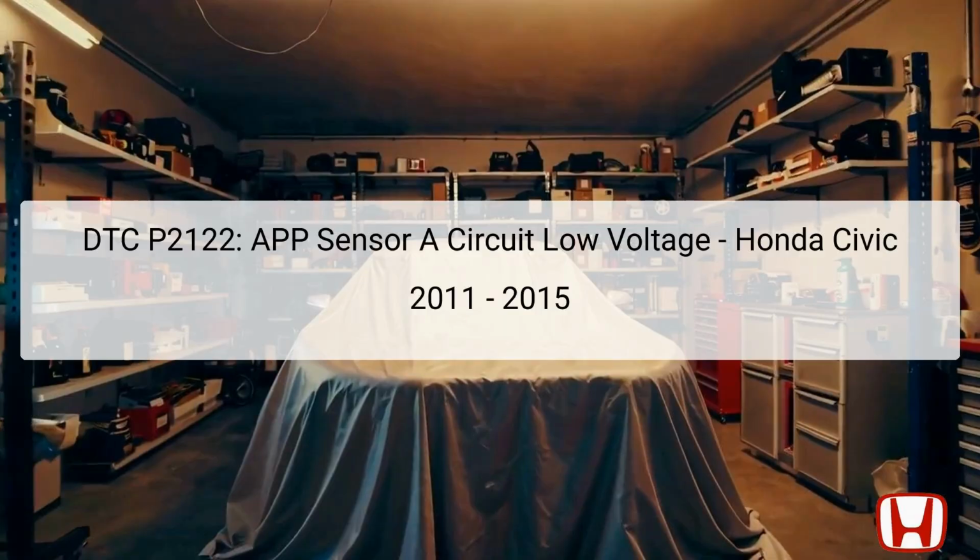Welcome to the troubleshooting presentation for DTC P2122, which stands for APP Sensor A, TP Sensor D Circuit Low Voltage, in the Honda Civic models from 2011 to 2015. This error code is associated with the malfunctioning of the Accelerator Pedal Position (APP) Sensor A, which plays a crucial role in providing throttle position information to the Engine Control Module (ECM).